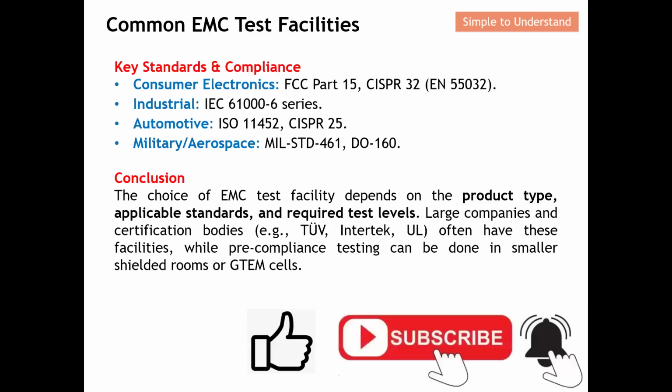Coming to more detail, these are all the key standards and compliance. Consumer electronics, we have the FCC Part 15, CISPR 32. Industry, we have this IEC 61000-6 series here. Automotive, we have ISO 11452 and also CISPR 25. As for mil spec, we have 461 and DO-160 here.